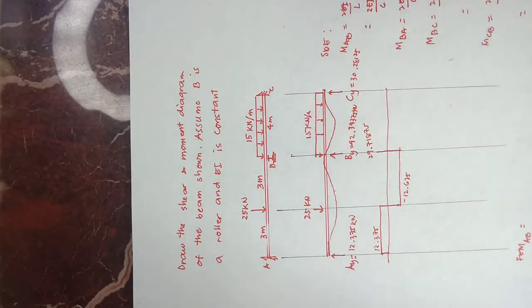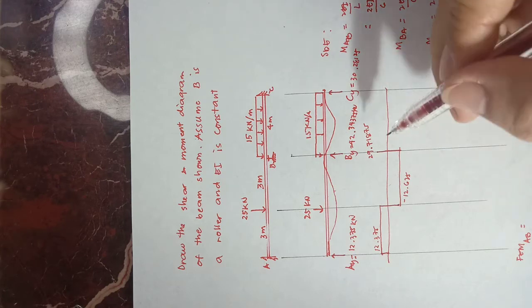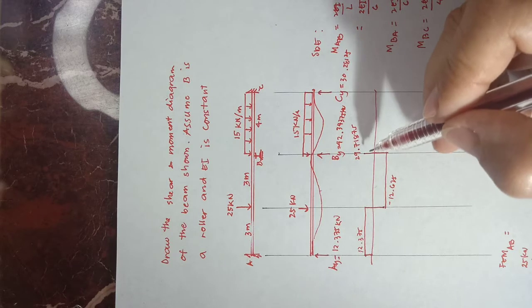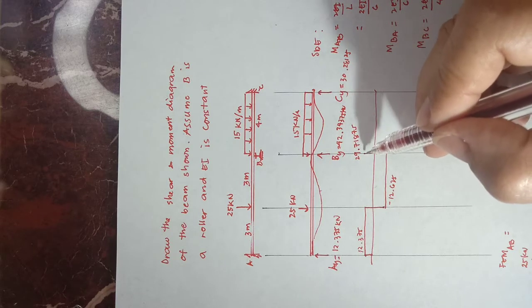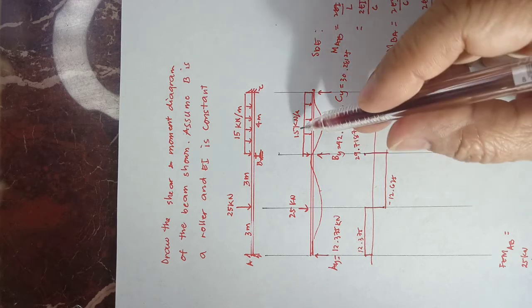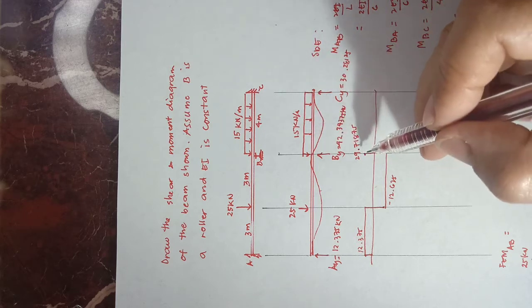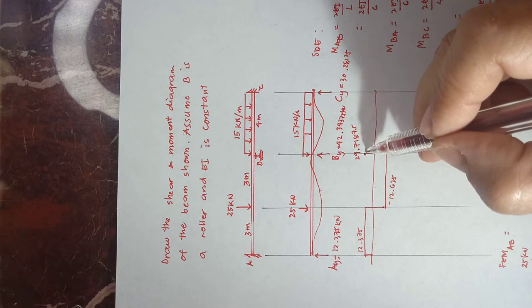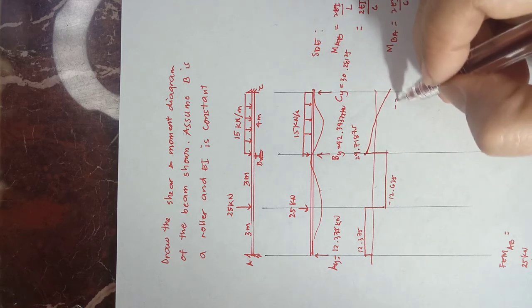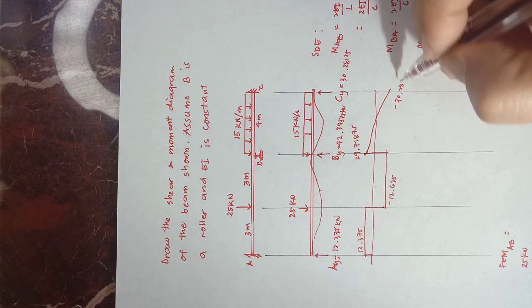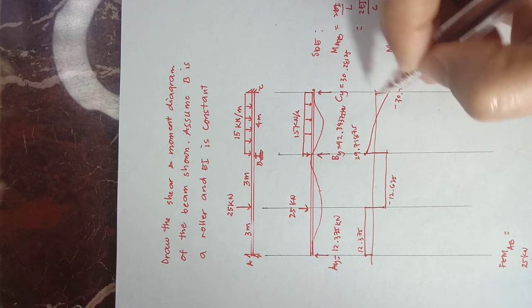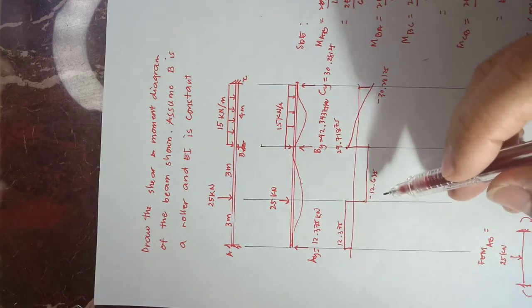29.71875. Okay. And then, you have a uniformly distributed load. So, linear ang imong reduction. Since that is downward, so minus. If you subtract it by 15 times 4, you will get a value equivalent to minus 30.28125. And then naa kay CY nga upward, so your shear diagram will close.